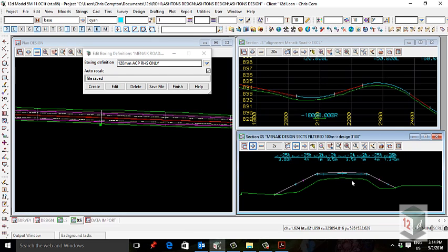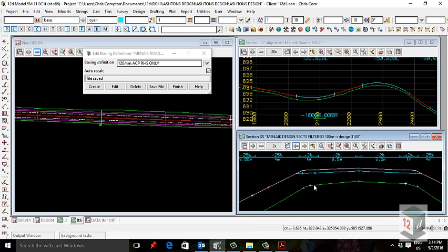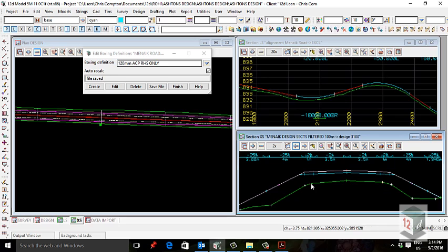So layer 2 is a little bit more complicated. Basically what we're doing is we're trying to use as much of the old formation as possible, and we're going to interface from this point here and interface with the tin on either side. This is demonstrated pretty well in the introduction of pavement overlay drawings, video number 3, but I'm just going to quickly reapply the functions for my client's benefit.